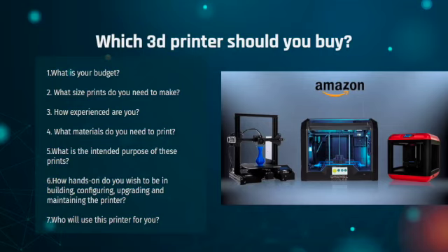What materials do you need to print? Most people are going to, at least at the start, print using a vegetable-based plastic called PLA, which I mentioned before. This is basically what most starters will use. But if you're more experienced, you might need flexibility and more toughness with other materials. So depending on the materials depends on some features you might need, like a heated bed, heat resistant parts, and the temperature your hot end can safely reach.